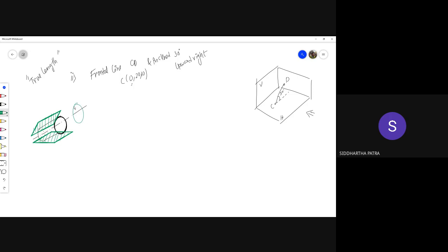So essentially there is one plane which is normal to this axis, and whatever other plane is normal to that normal plane is going to be parallel. Since there are infinite number of planes which could be normal to a given plane, therefore there are infinite number of planes which are parallel to a given straight line. For example, whether you project a vertical line on the xz plane or yz plane, you still get the true length.